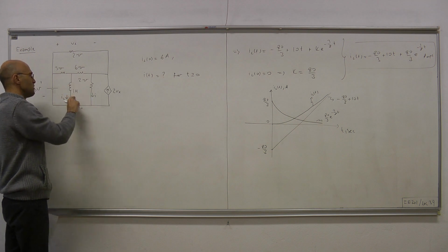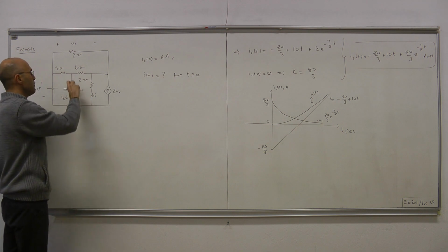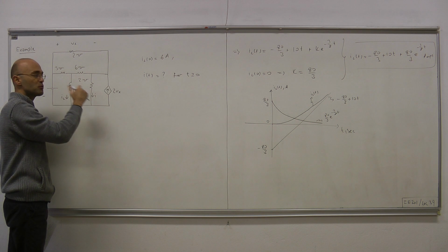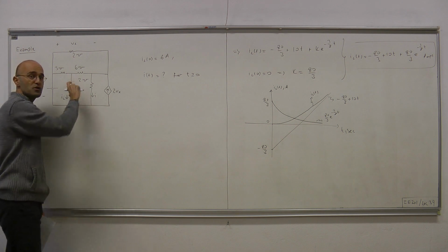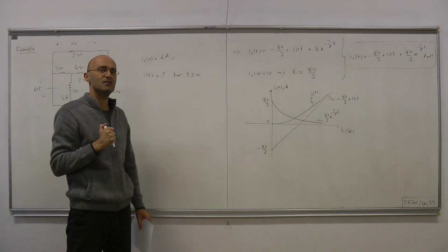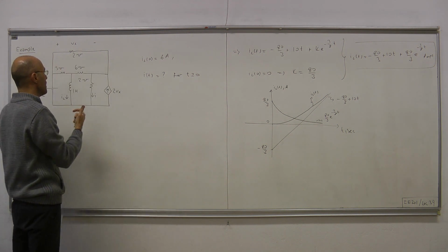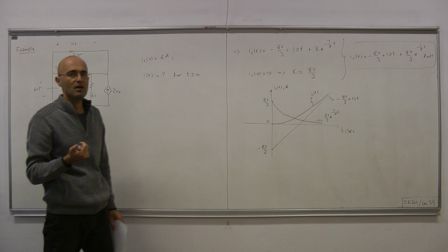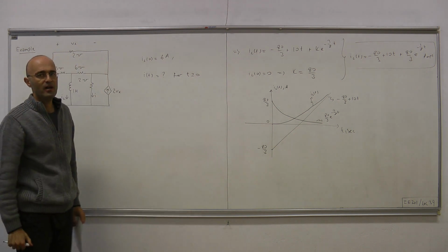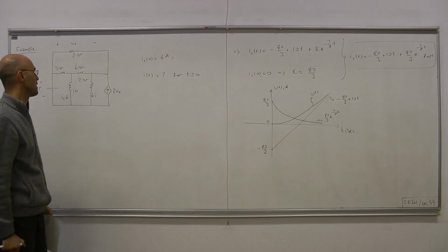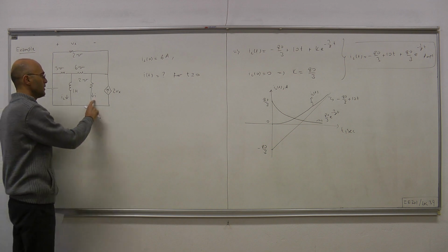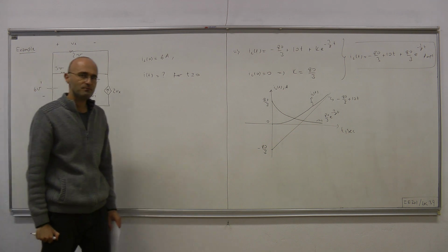Therefore, we can substitute this dynamic component either by a current source which provides IL(t), or a voltage source which provides VL(t), and then the circuit becomes an LTI resistive circuit. For that circuit, just apply your favorite method, node analysis, mesh analysis, or something else, to figure out the current that you asked for.